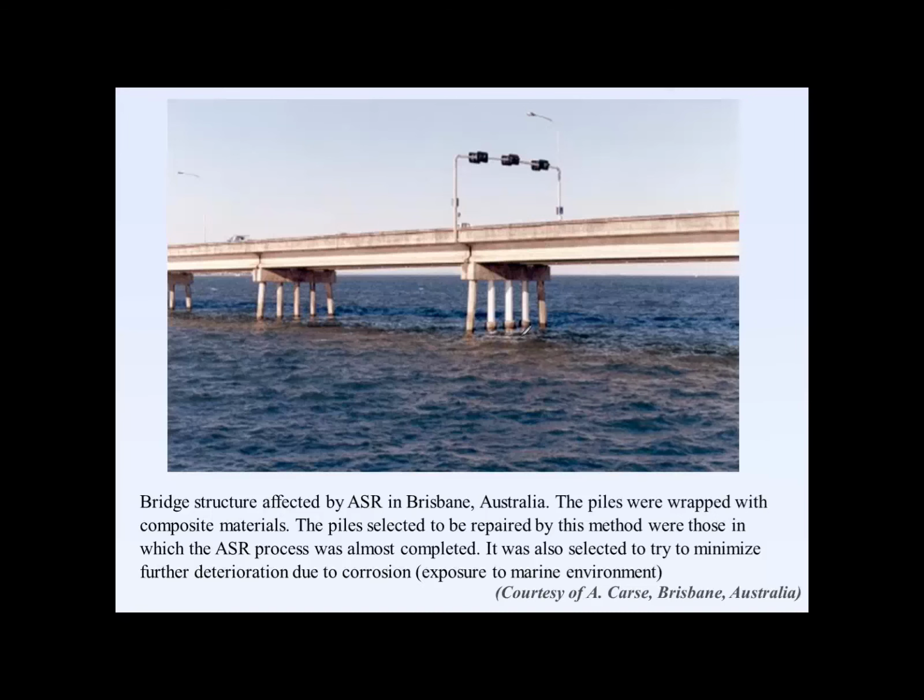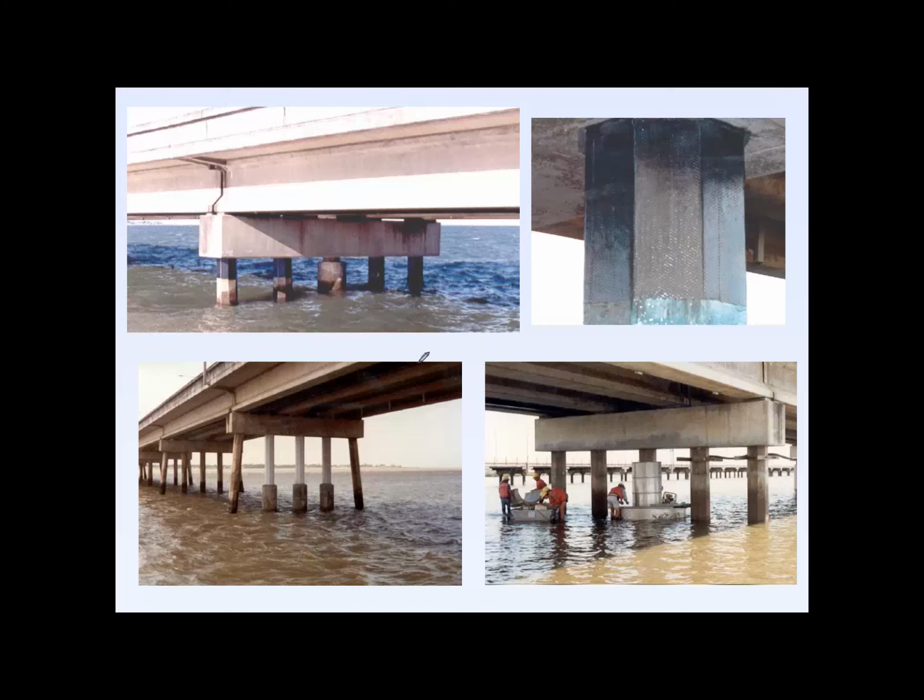And lastly, I'll just give a few examples of columns, which are probably the most common in terms of the application of external restraint. Here's an example from Australia where you had ASR-affected columns in a marine environment. And what was done here was a series of different repair jobs where you can see that here's a case where an external concrete jacket was applied. You can see them right here. And you can also see in the upper right-hand corner the application of FRP wraps themselves.